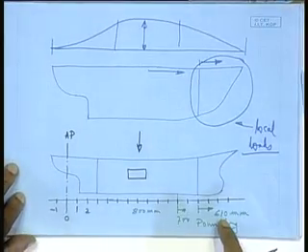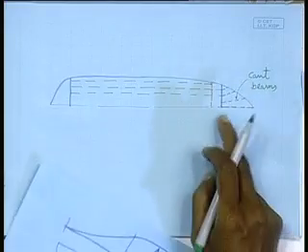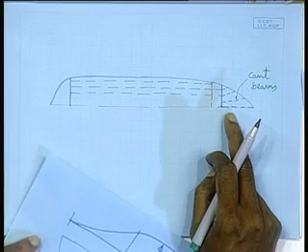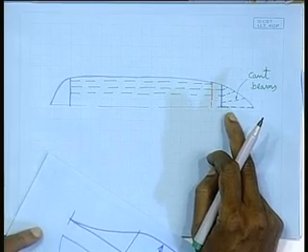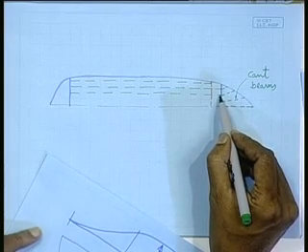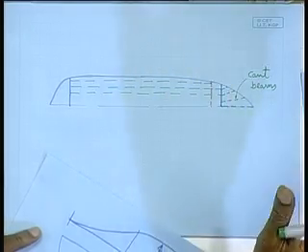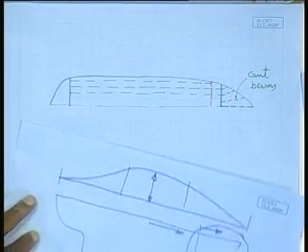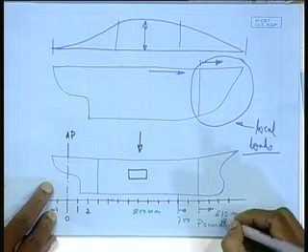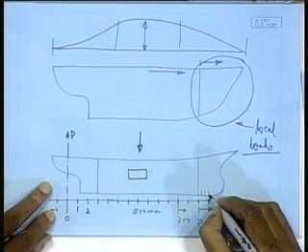We came from 610 millimeter frame spacing. So, the spacing of cant beam, you see, it does not follow 800 nor 700 nor 600. It is starting at a frame spacing of, here, well, it would be 700 or 800, right? And then it is radially going out. So, that is not creating any problem. So, here 610 is primarily for the transverse members, whatever is coming.